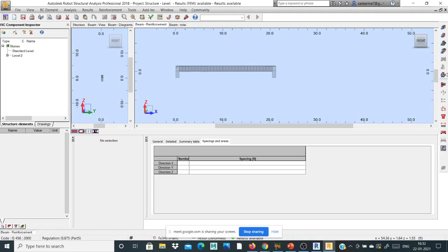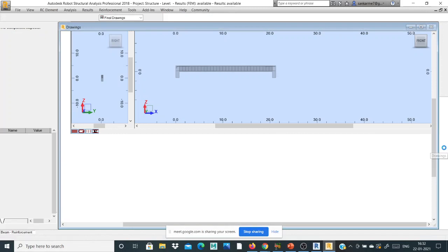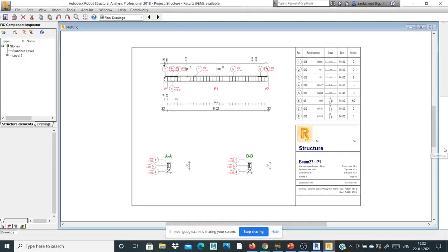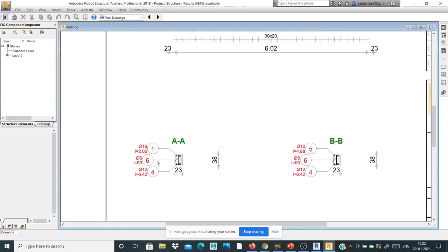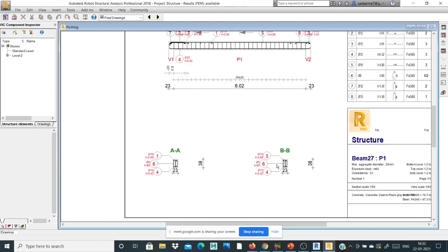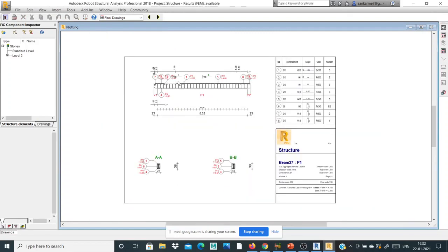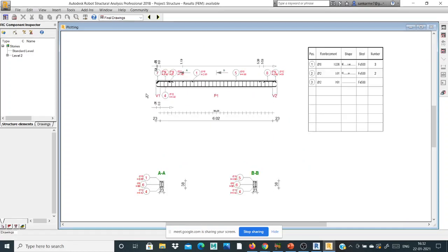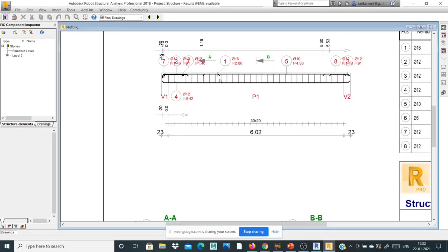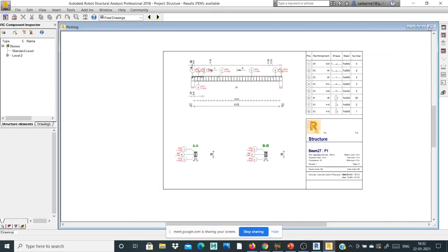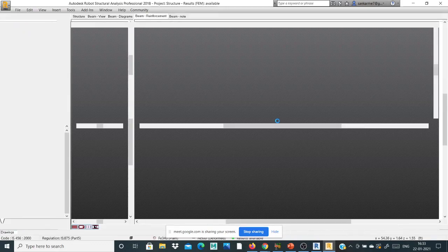Toolbar menu. Then go to the drawings option, right? Simply click this drawing option. See this. It is automatically converted into your beam cross section and longitudinal section. Simply click this drawing section, and our beam longitudinal section, cut-off length, all the lengths will be converted into a sheet, right? Now you understand how to create the beams and so on, right?